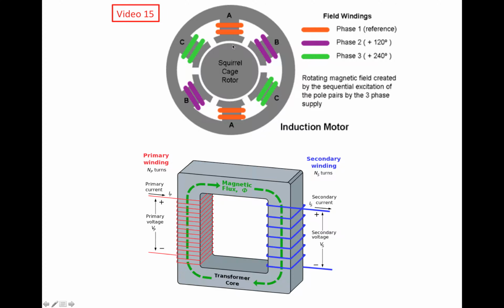If the rotor of the induction machine is not rotating, either because the end rings are open so there's no current flowing inside of it, or because we are holding it stationary, under those kinds of situations, the induction machine is actually almost identical to another type of electrical machine known as the transformer.